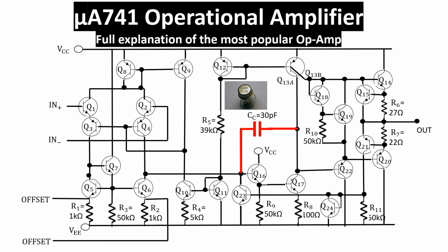However, speaking about the uA741, we must give credit to Bob Widlar too, because the schematic is based on the LM101 designed by Bob Widlar for National Semiconductor, which in turn is based on the uA709 and the uA702, the first monolithic IC operational amplifiers, also designed by Bob Widlar for Fairchild Semiconductor. We are going to show the general working of each single part of the schematic, and then we go deeper, calculating some important characteristics of this OpAmp.